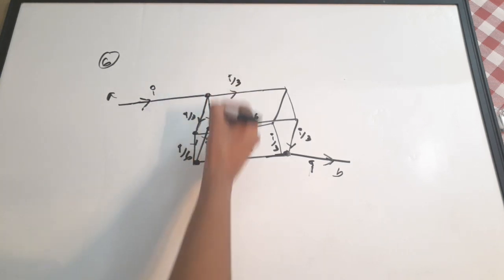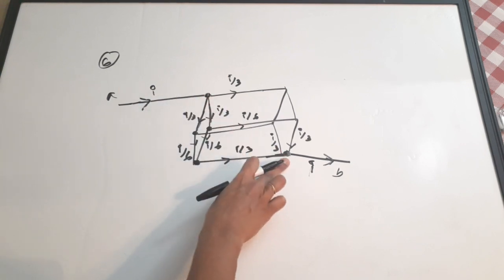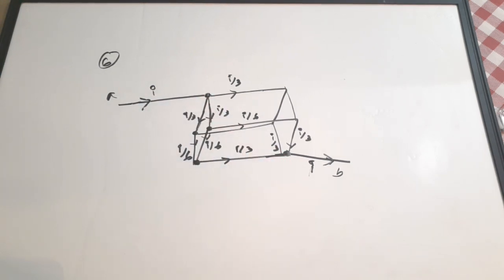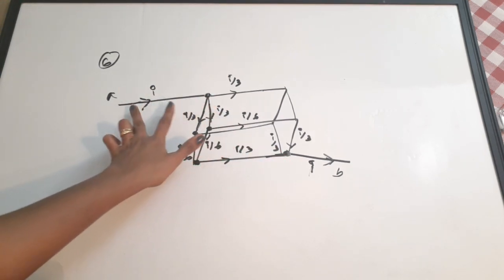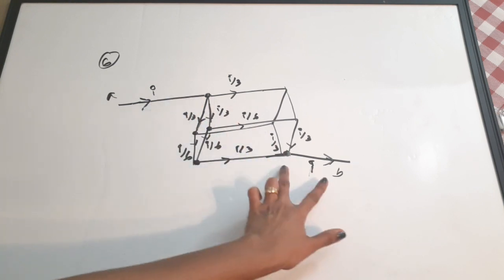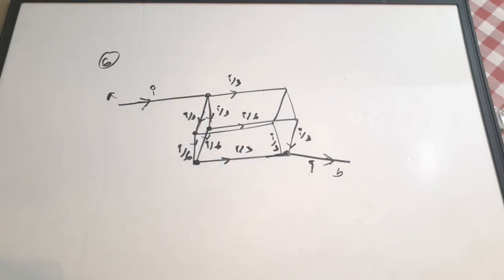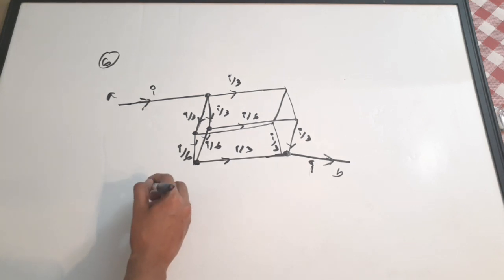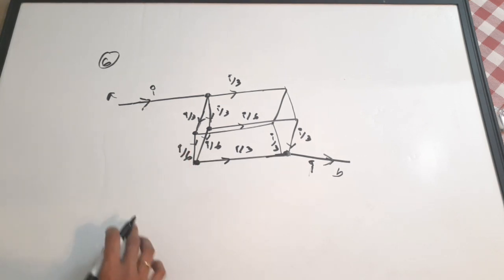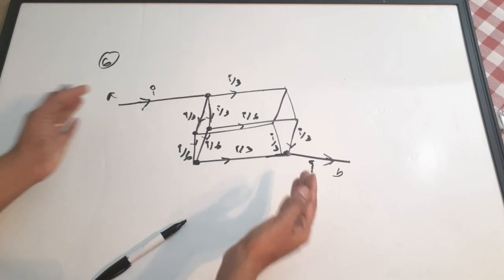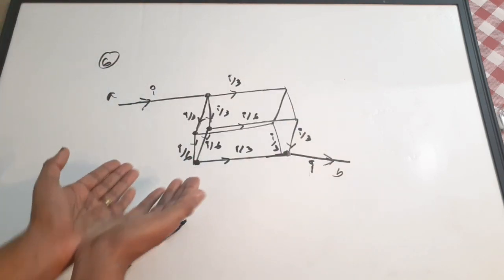Now take the corners or diagonal points, this and this. I'm going to take the voltage at this node as A and at this node as B. Now I'm going to apply KVL along the diagonal. That is, if you take these two edges and combine as a loop, you can apply KVL.